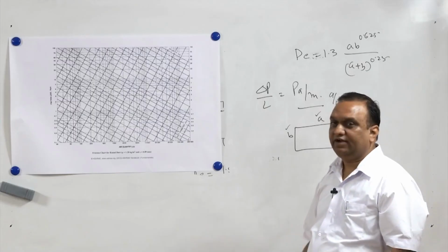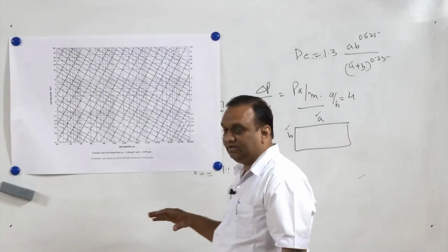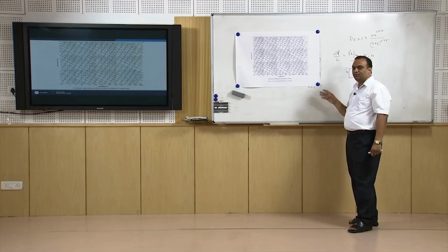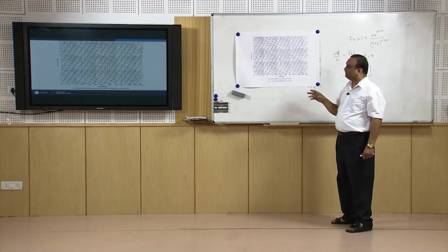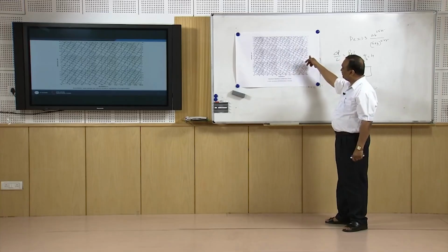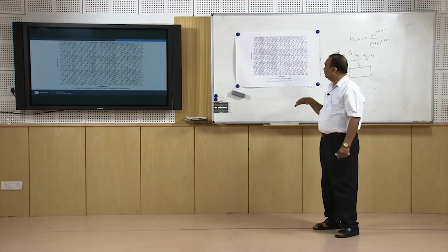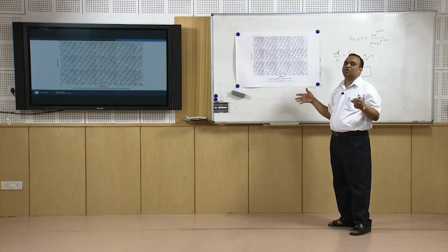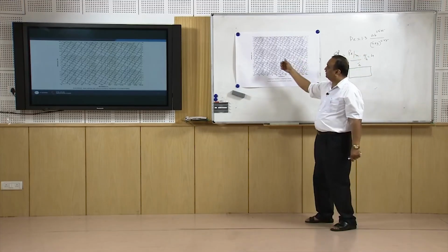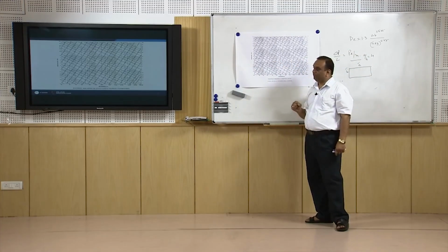So, in the network of ducts, there are going to be ducts of different length and different discharge. For that network of ducts, we can find the diameter of individual duct using this chart. In addition to that, using this chart, we can find the total pressure drop in the system, which will help us in deciding the size of air handling unit.